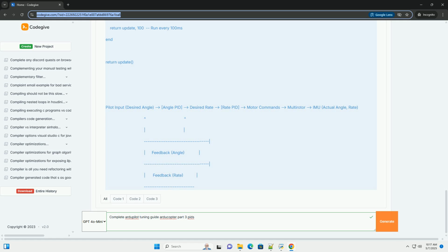Important auto-tune caveats. Ensure adequate battery voltage. Auto-tune puts the drone through hard maneuvers, so a weak battery will yield poor results. Be ready to take over. The auto-tune can fail, and you will want to be ready to put the drone into a stabilized flight mode. Check weather. If it is windy, or if there are sudden gusts of wind, do not use auto-tune. Monitor battery voltage. As stated above, auto-tune can be hard on the battery, so pay attention to the voltage to avoid a crash.